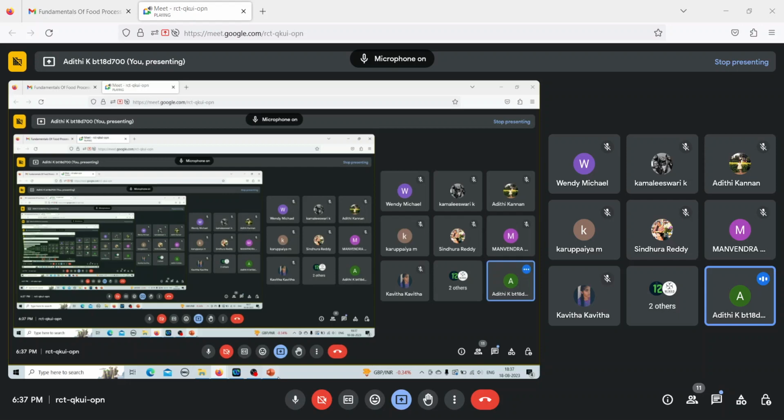So you can actually add up the resistances: 1 by U is equal to 1 by U1 plus 1 by U2 plus 1 by U3. You can add the resistance in each of the effects to find the total resistance. And when you look at the first effect evaporator alone, you can say that Q by A is equal to U1 into delta T1. Is this part clear? Is it getting too confusing?